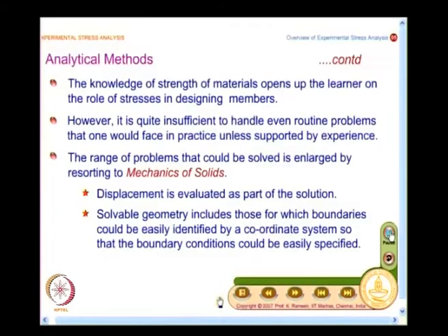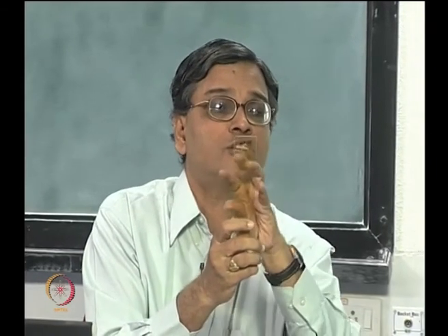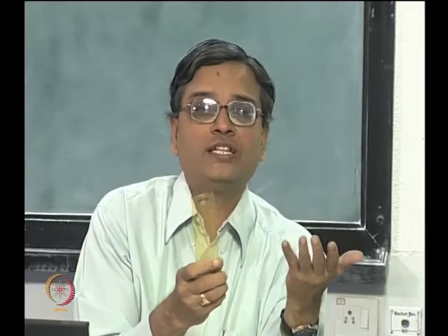So, when I go to theory of elasticity, where I am able to idealize, I look at a situation where I remove the restriction on displacements and I evaluate displacement as part of the solution. Even there I need to have infinite boundaries for a problem like this, only then would I be able to solve. Mathematically the distances are far away, but physically it could be a very small hole. This closely resembles it, and this solution is possible. And plate with a hole is a very, very important problem.